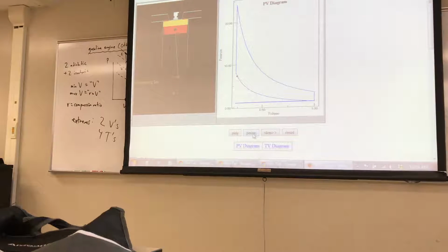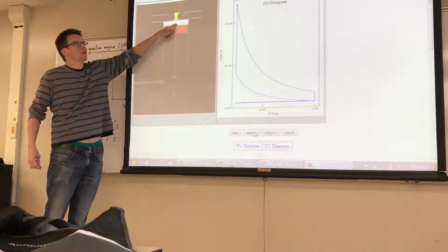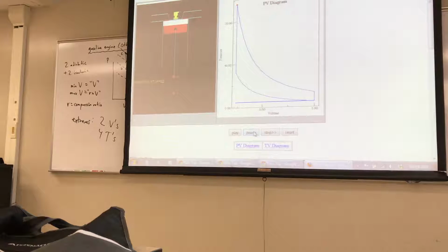Next step. We're going to increase the temperature even more, basically by putting in heat. Where does that come from? Lighting up the gas. The spark plug goes off, which creates a spark, and it combusts the fuel, and that combustion is going to release more heat. So, here we go. Boom. Notice that the spark plug, which is right here, has ignited the gas. That has put more heat into the system, and since that combustion happened very rapidly, the gas doesn't really have much of a chance to change its volume. It's happening on a much faster time scale than the piston is moving.